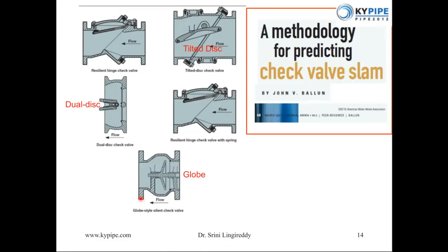The other types of valves, again, like I said, scores of different configurations have been developed by the manufacturers. The sole purpose of all of that is to minimize the reverse flow. For example, here, this is a slanted disc. If this construction was not there, the disc would have to travel from here all the way down here, the vertical.